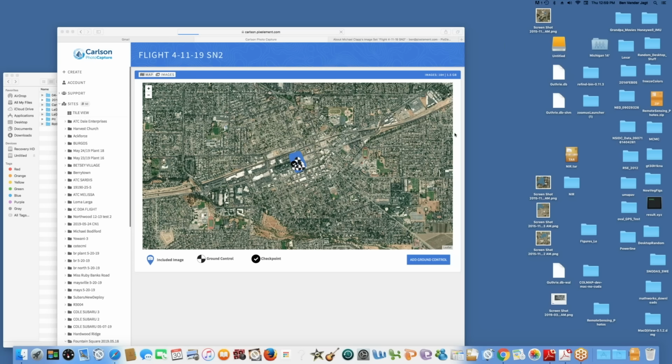And then the last question is from Gus. He says, can you get 1 centimeter vertical accuracy? What I would say, Gus, is that that's going to be tough, only because the accuracy of GPS observations in general, especially kinematic observations, is really plus or minus 2 centimeters. If you sit on a point for a longer period of time, it might get better.